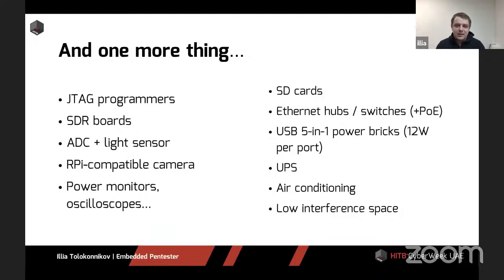Developing on top of that idea, this is a setup we almost put into production. The Raspberry Pi has a 2-megapixel compatible camera that you can connect to it. So when you have some kind of display on your device, or maybe even a light indicator that can change colors, you can put those things in some kind of isolated box and run either a photo or video stream over that camera. If it's a video stream, put it through FFmpeg, and then those images can be run through some kind of OpenCV recognition or even a simple neural network.